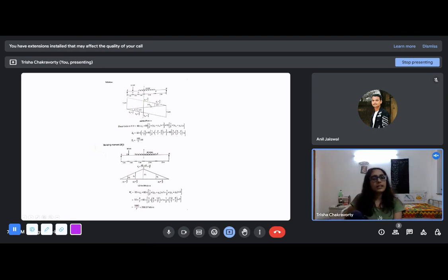When you're finding the area, you can just use the properties of geometry, the kind of things you know. So for the point load, it is the magnitude of the point load into the ordinate, and for a distributed load, we use the magnitude of the distributed load into the area. This is how we do it. Don't forget the signs, because these cancel each other out. This is a negative one, this is a negative one, and this zone has a positive influence.